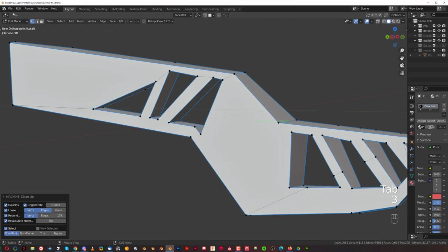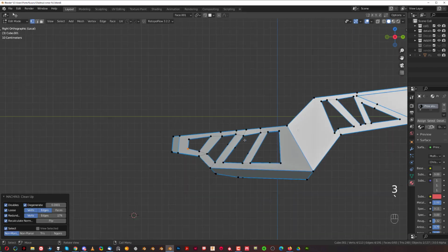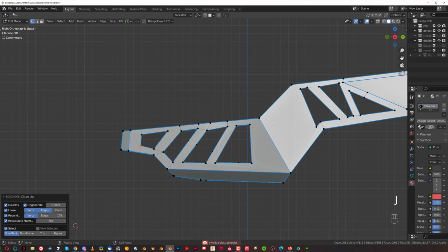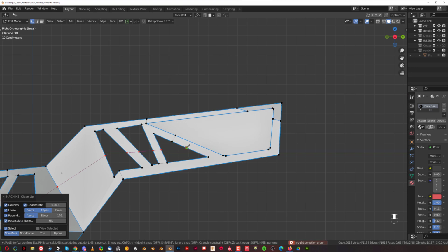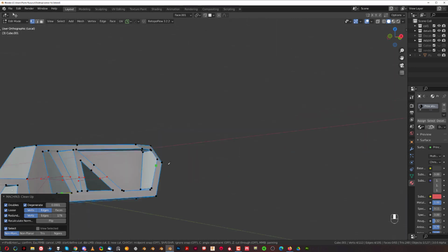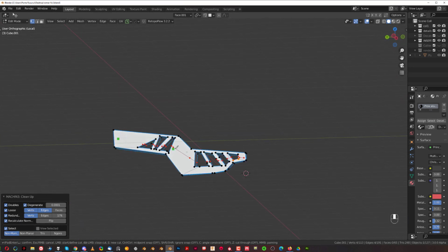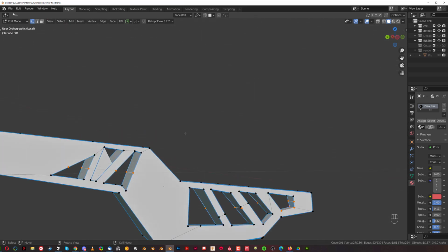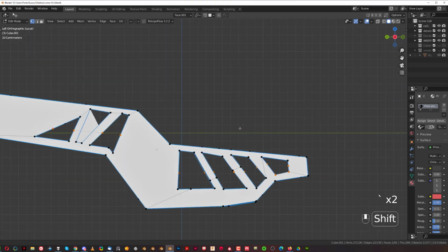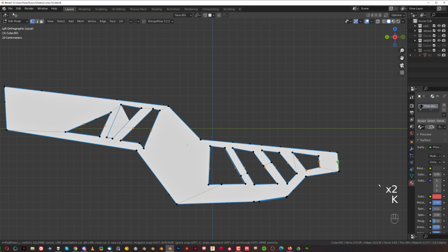let's just clean it. Now, of course, I'm gonna be running different edges because this is a mess here with edges. So we're gonna be running our private edges here, personal private edges like this, through the entire mesh, right? Like this, and then press E, turn it around, right? Or maybe even apply this and then go to the other side and run another edge here. So, run it like this, like that.